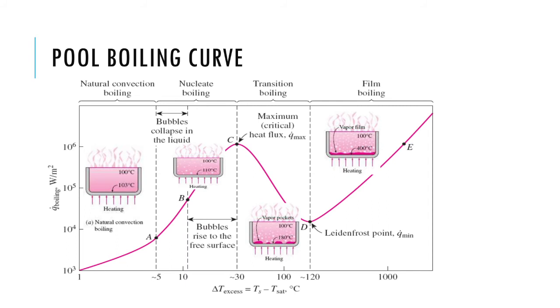Now one may ask, as this graph is showing, at first from O to A it increases as boiling has just started, A to B bubbles start, B to C bubbles go up at an increased rate, and C to D the film forms which acts as a thermal resistance. Then the graph should keep on going down. One may ask, why does it go up from D to E? This is actually a very good question and there is a very interesting reason behind it.